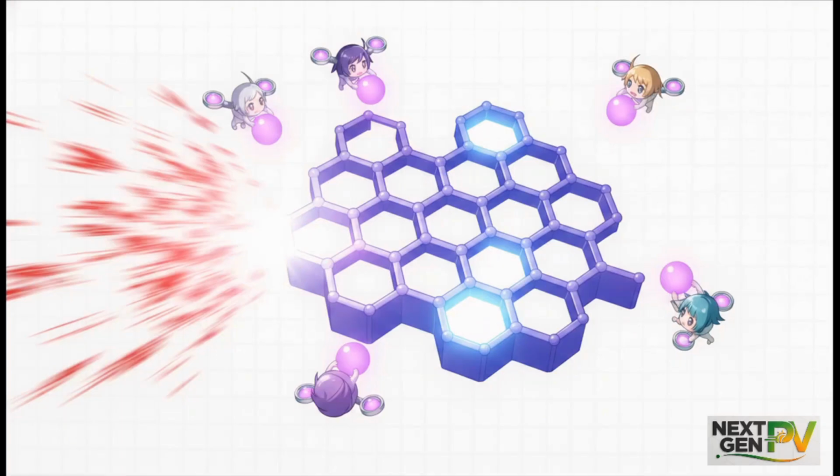Another brilliant tactic is direct vacancy filling. Missing iodide ions are one of the most common defects, creating literal empty spaces right in the crystal lattice. If we apply passivation molecules that contain iodide themselves, like PEAI or potassium iodide, they act like a microscopic delivery service. They supply the extra iodide ions needed to physically plug those empty vacancies. And not only does this eliminate the trap state, but it actively stops other ions from migrating through the empty spaces, which vastly reduces performance hysteresis and improves the cell's overall stability.